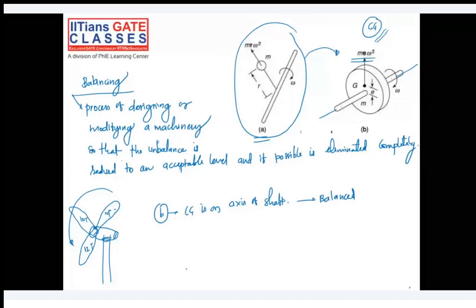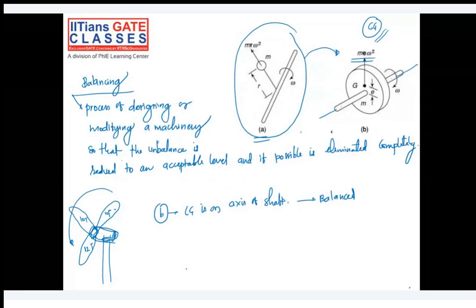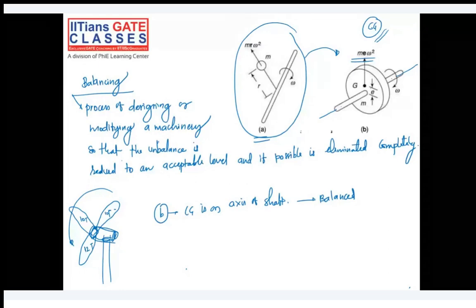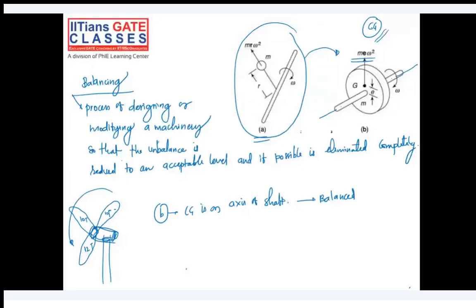This rotor is connected to the main bearing, so loads on the main bearing will increase, and ultimately it will cause damage to the main shaft and all the other components linked to it. That is why it's very important to balance the system and to make sure that the center of rotation, or the CG of this rotor, is exactly along the axis of rotation. Otherwise we can come across some serious problems.